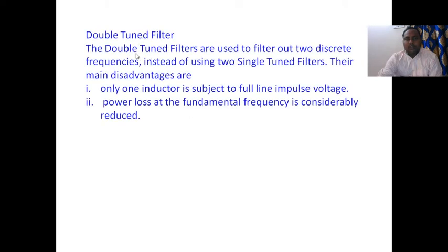Double tune filters. The double tune filters are used to filter out two discrete frequencies instead of using two single tune filters. Their main advantages are: first, only one inductor is subjected to full line impulse voltage. Second, power loss at the fundamental frequency is considerably reduced.